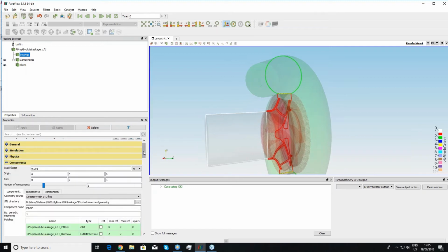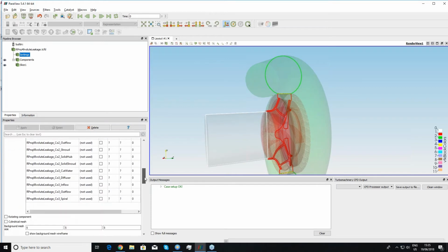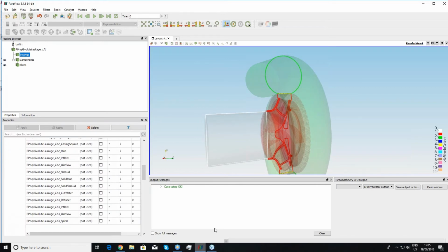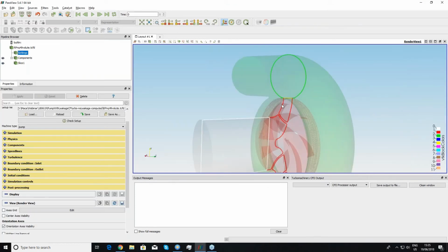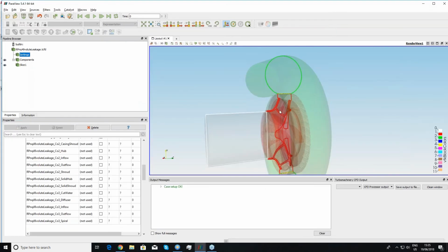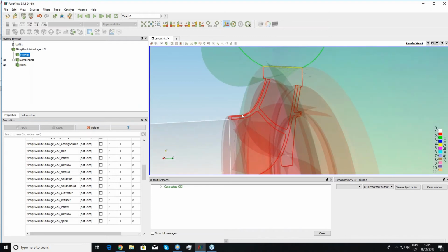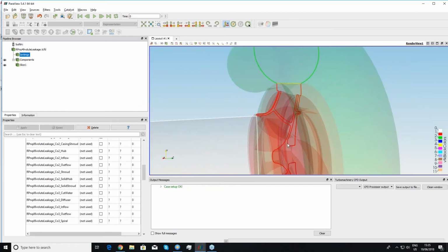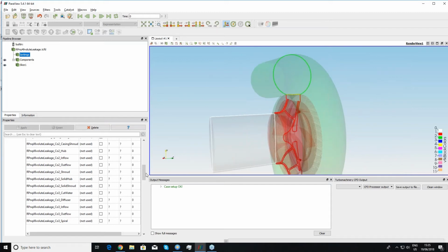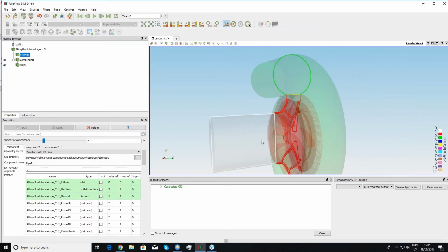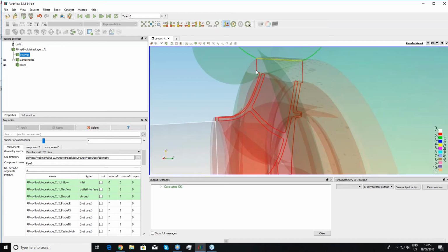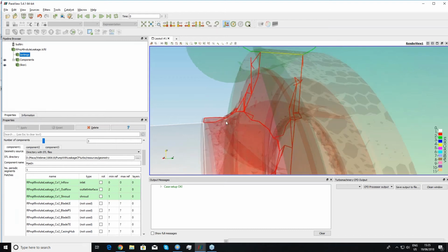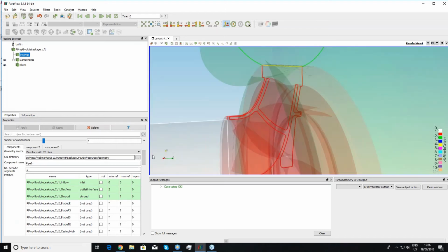Inside the components, from CFturbo we get almost the same, or at least very similar, geometries. We only have some additions, such as these solid walls defining the leakage parts, both at the shroud side and hub side. So this is the only difference between these two cases, and of course we need a finer mesh here to really have a nice and fine mesh in the leakages.